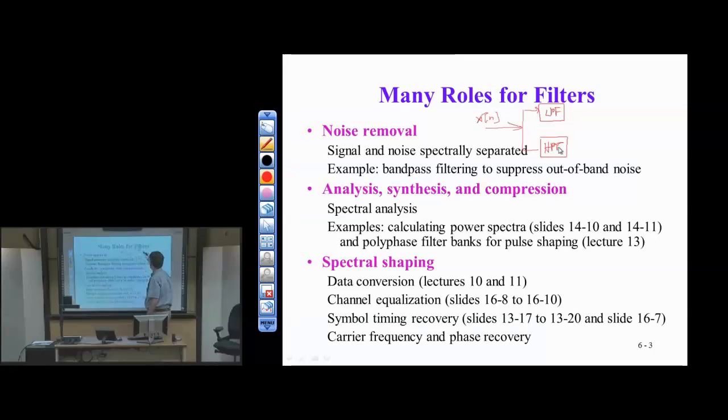And this is analysis. This breaks a signal into simpler or smaller bands. An example low-pass filter could be an averaging filter. We could have a 2-tap averaging filter, just for simplicity, but any low-pass filter will do. And for the high-pass filter, we could have a first-order difference.